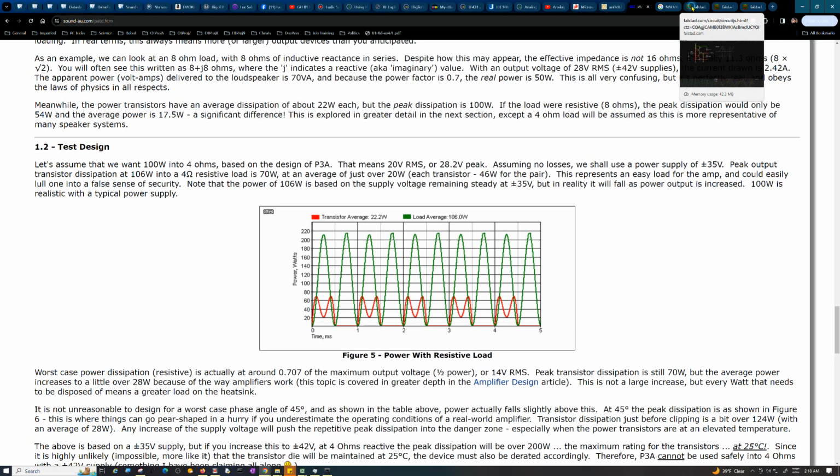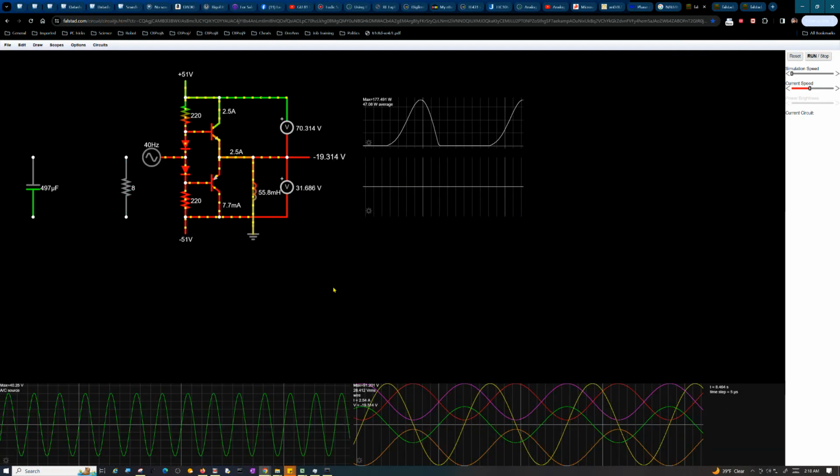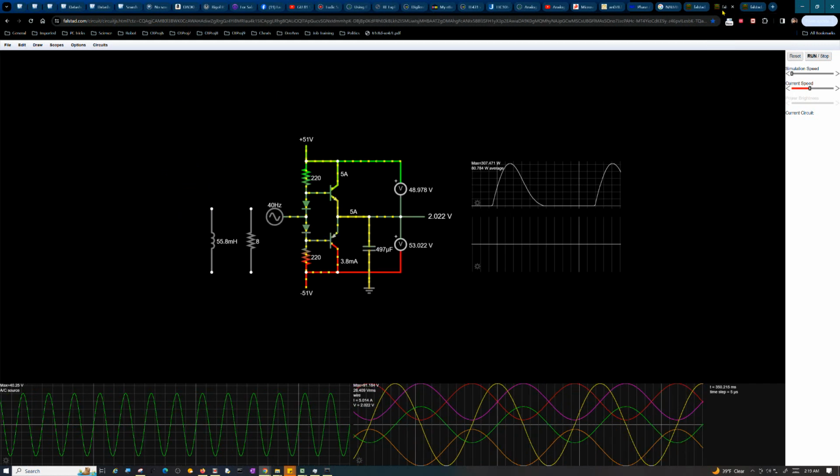So, I found one of their generic circuits and modified it to run tests on it, and this is with an inductive load. Now, all my inductances, I'm only using 40 hertz and the 1 kilohertz he talked about there. But I got these all tuned to where they're basically 8 ohms of impedance at 40 hertz, because the theory should apply, which just happens to be, at 8 ohms, the corner frequency of 40 hertz, as it turns out. They talk about it being at a 45-degree phase angle, which is honestly a hallmark: when you get a 45-degree phase angle, that's your corner frequency of a filter.